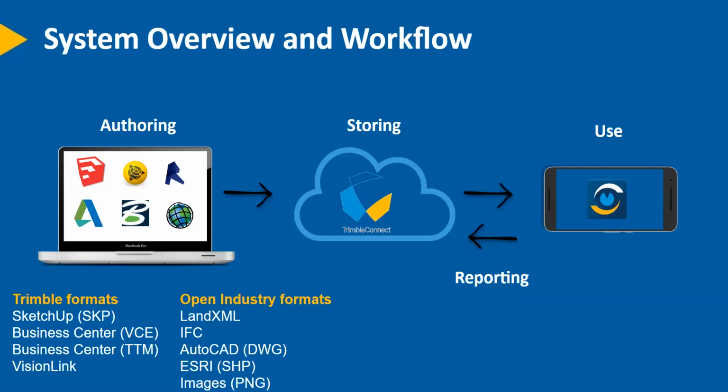So in our case, the Trimble Connect cloud application, which I mentioned earlier, is our go-between between the authoring tool and the actual use of that data in the field by Sight Vision on the far right there. You can exchange data between those authoring tools and Sight Vision in standard industry formats like LandXML, IFCs, CAD drawings, shape files, even to enhance the augmented reality and provide additional context.